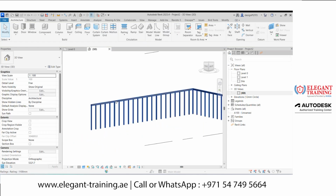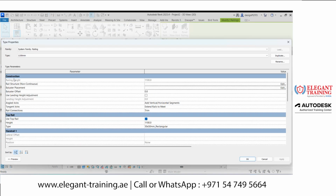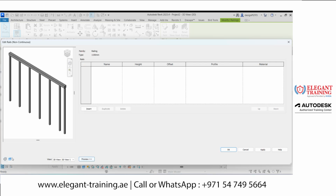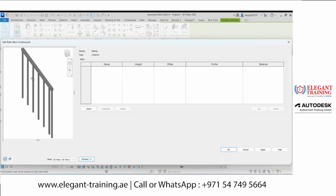If I select this railing and go to Edit Type, under Construction I have the options Baluster Placement and Rail Structure. These are the two important things you need to take care of. If I edit the rail structure and enable the preview, this is the preview. In the preview you can also rotate it.